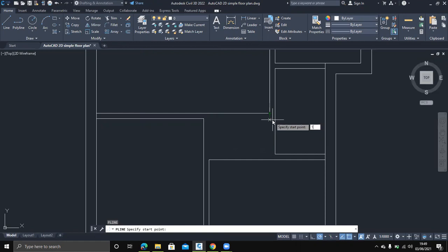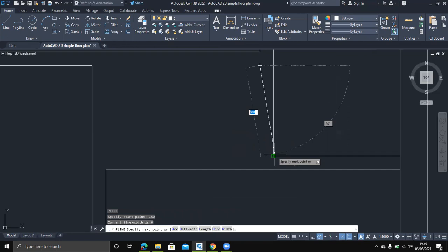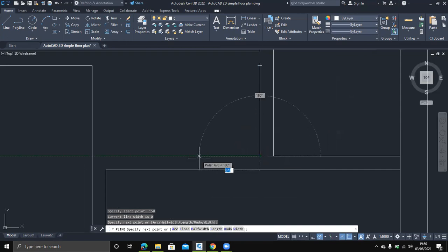I will draw an extension of 150 units from there, and then I will snap that there. And then this length right here, this is where I'm going to apply object snap tracking a lot. So I will trace this line here from this corner using object snap tracking, where it snaps the horizontal and the vertical, where the object snaps meet. I will just click there, and you can see that line will have been drawn at that point.